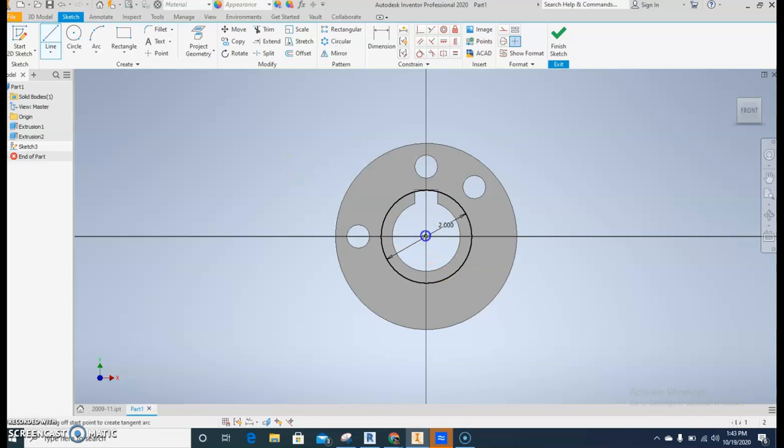And here's what you need to do. Go down here and go down 0.5. Draw that over to here. Okay. Now, if this doesn't activate the outside, just hit Project Geometry and click the outside line because we need that to be on. Next, we need to draw a line straight up from here, 0.25, and then go over this way. And make sure you go straight.